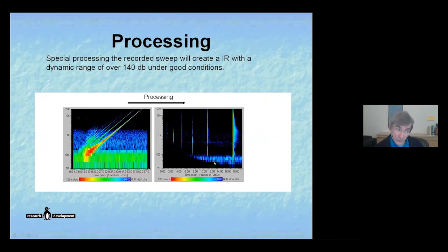This is the test signal. What I said is very important, the test signal. Spend a lot of time in finding the right test signal, because there is distortion from the box, and this is the sweep, and the backwards processing, the convolution with the inverse filter, brings you, only if you have a long sweep, which is about double the time of the reverberation time, and then you can cut off the distortion. These are the phantom things here. You can cut them off.